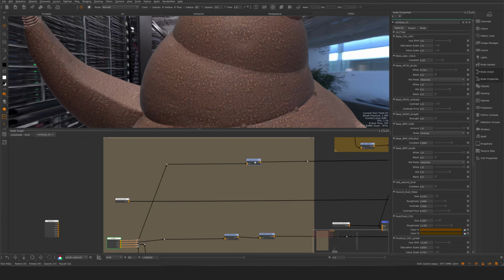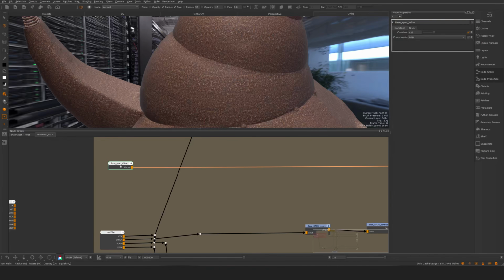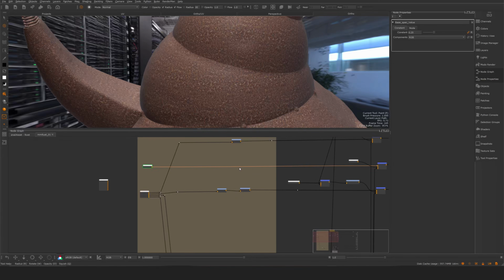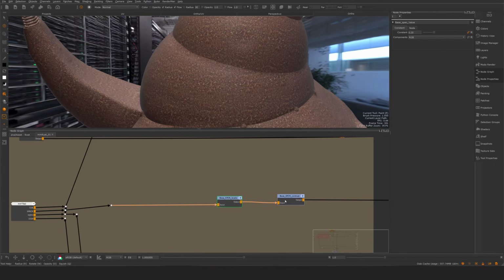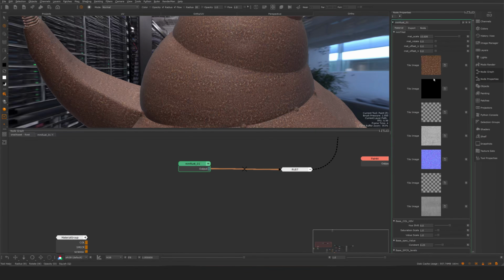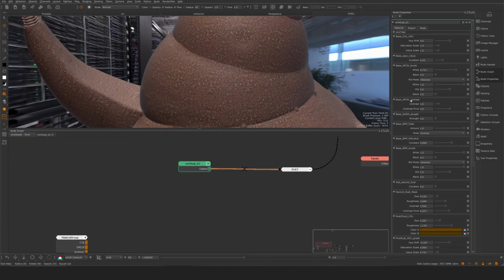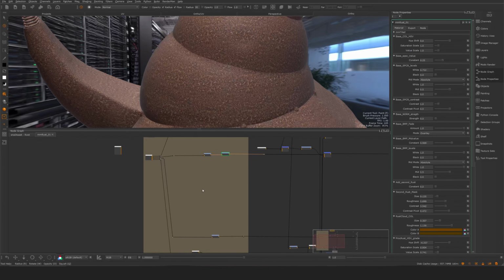I have HSV overrides, we have base specular, and that's just a float value coming in. We also have, for the specular roughness, the base spec R levels and a contrast operation that we can create on top. In the interface, they are essentially here, levels and contrast. I have normal strengths, but I am not using normal maps in my material at the moment, so we can disregard that. I'm using displacement and bump.